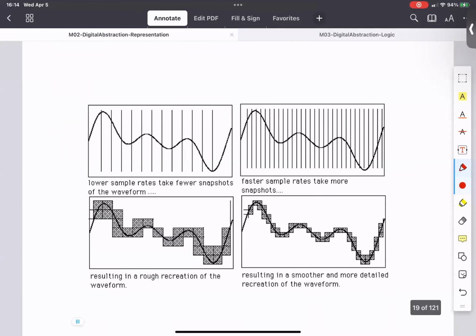Intuitively, you might say, okay, if I sample it more frequently, then I probably have less information loss. Stands to reason. And likewise, if I sample it more finely in terms of the value, let's say if instead of dividing it into 10 bins, I map it into 100 bins, I will get a more fine-grained representation. Both of these things intuitively stand to reason. Now, let's talk about what the implications are on these two sides.